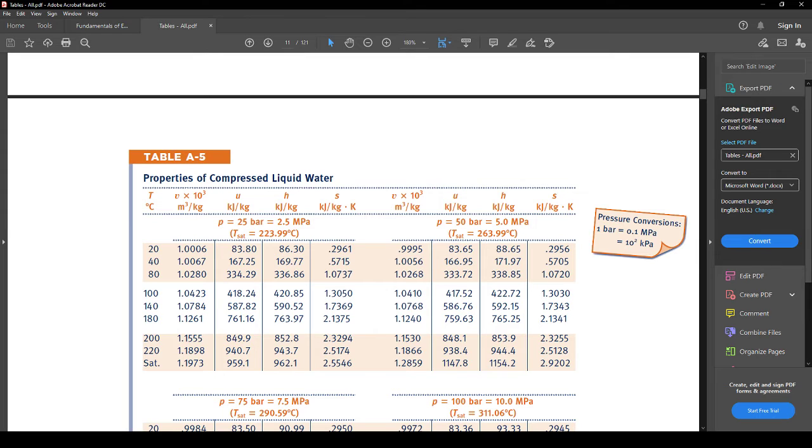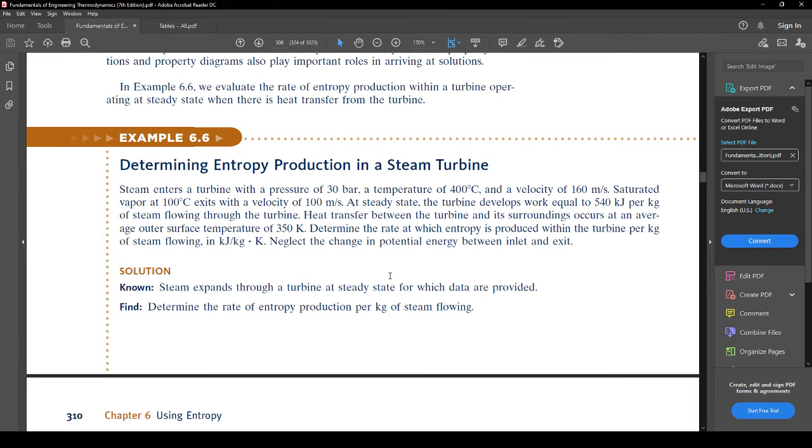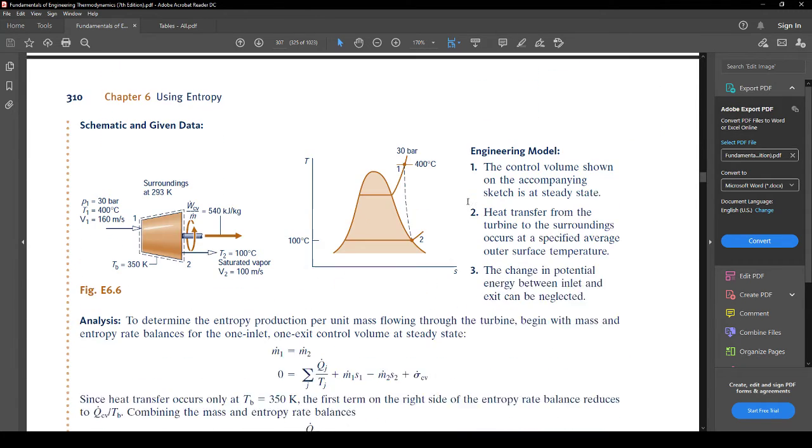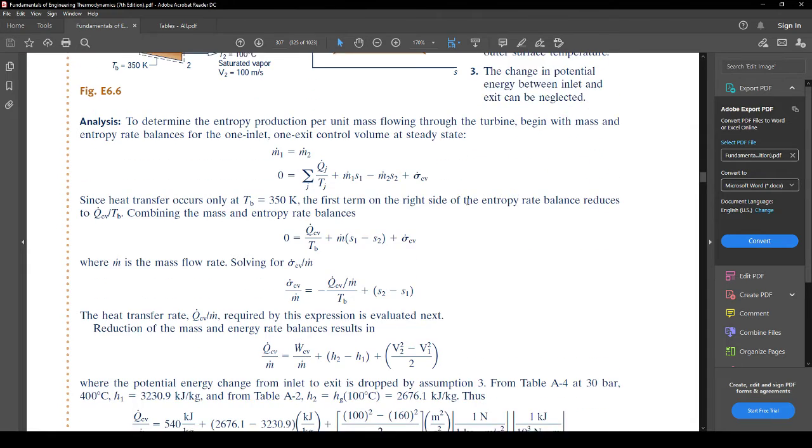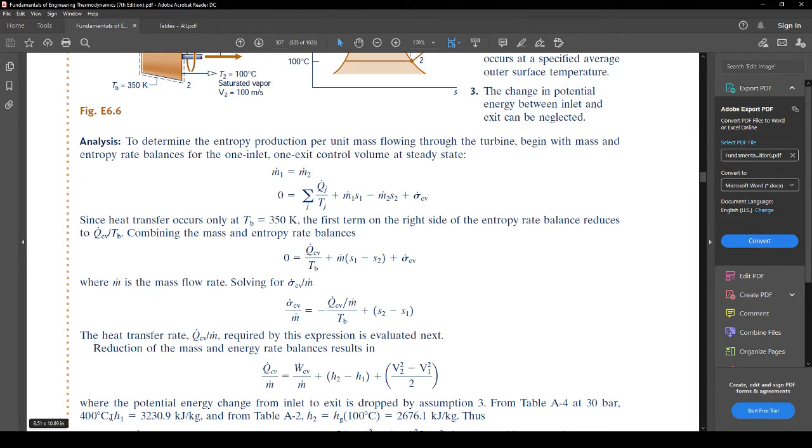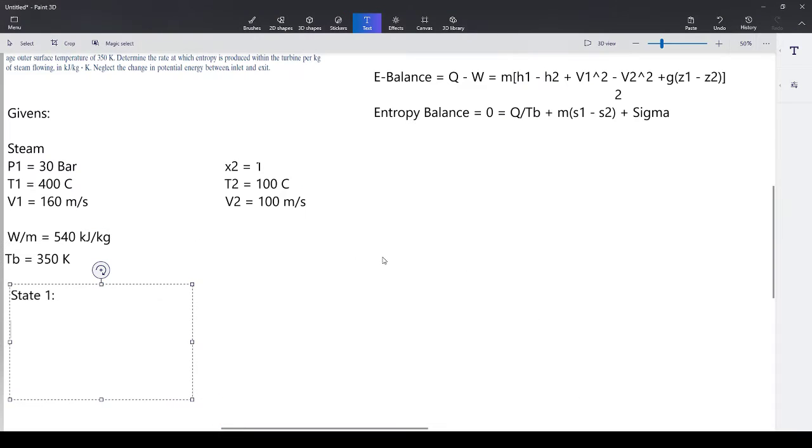Classic. So what we're going to do is I might just look at the solution to see, like here, because I don't really want to interpolate that. On exams, I'll try not to ever let that happen. But let's see what they do. So right here, they say that H1 is equal to 3230 from the table. So if you did interpolation using different lines, you would be able to find that. So you were right. We find H1 is equal to 3230 kilojoules per kilogram.